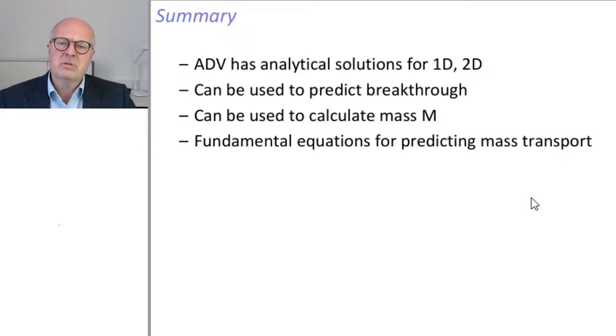And this is possible because the spread between the tracer not being seen anymore and detection is quite high. So let's remember the detection limit for Eosin is 0.002 milligram per cubic meter, or 0.002 microgram per liter.